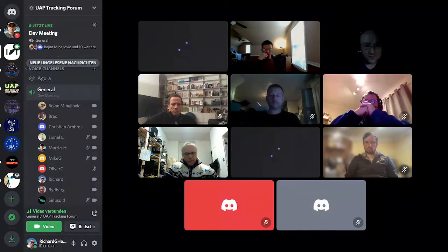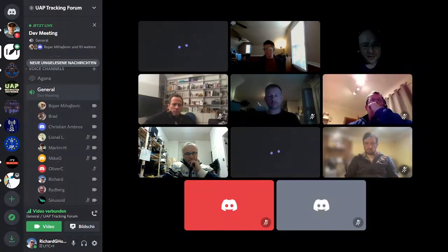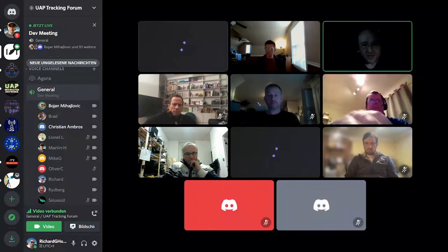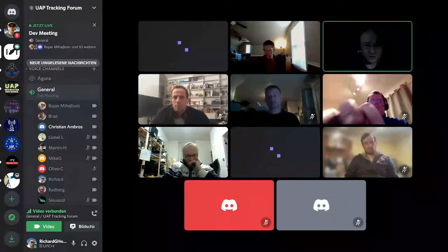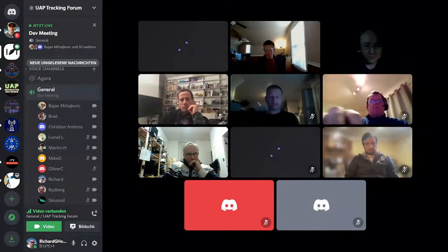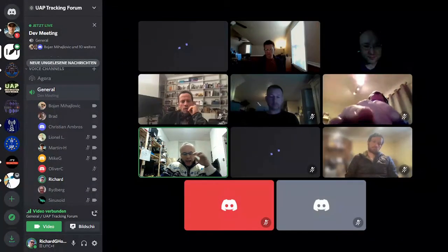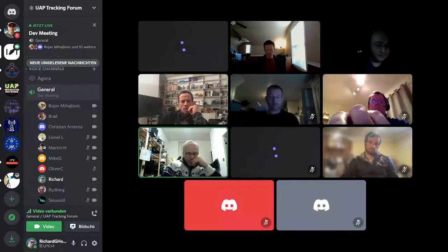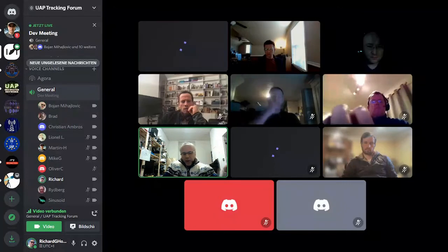Anders here, I have a question. The Raspberry Pi HQ camera, that's not usable here, or? Not really, because the diameter of the optics has to have a certain size because of the resolution. Okay. And the covered chip area is way too small. It just has, I think, 2 megapixels, and we need many more pixels, and they have to be very small for the resolution. So all these combinations of several small webcams, like the Wyze cams which were discussed some weeks ago, don't make sense, because if the resolution of the optics is too small, you just don't resolve this stuff, no matter how much resolution your sensor has.